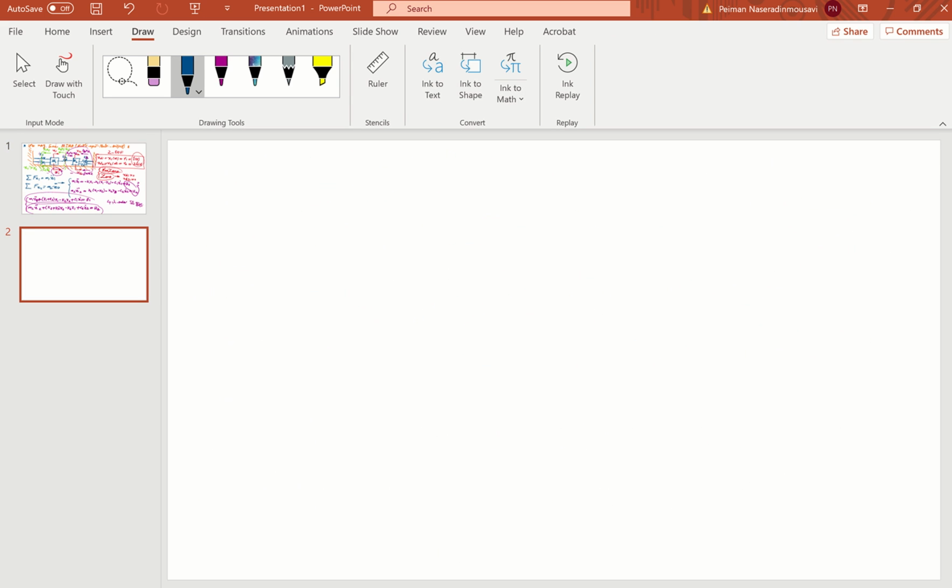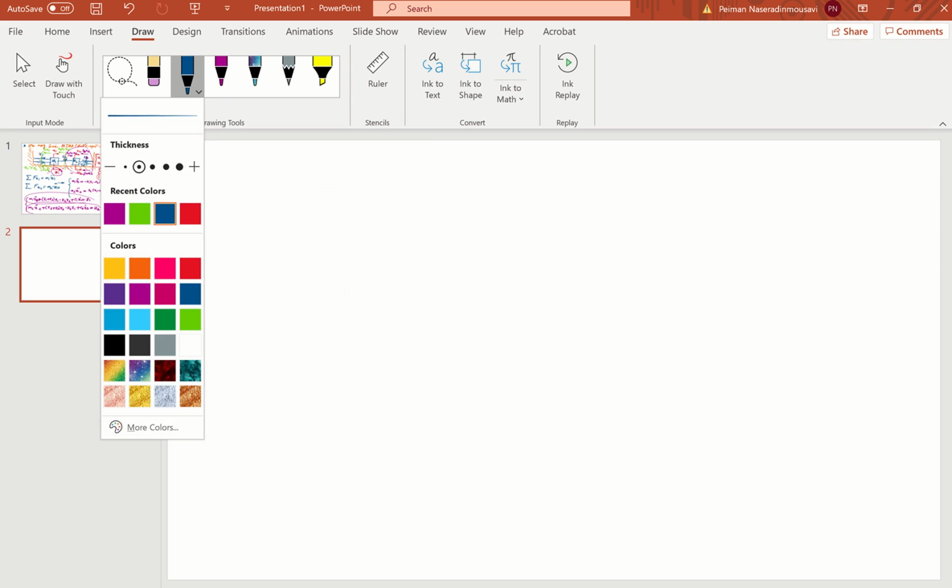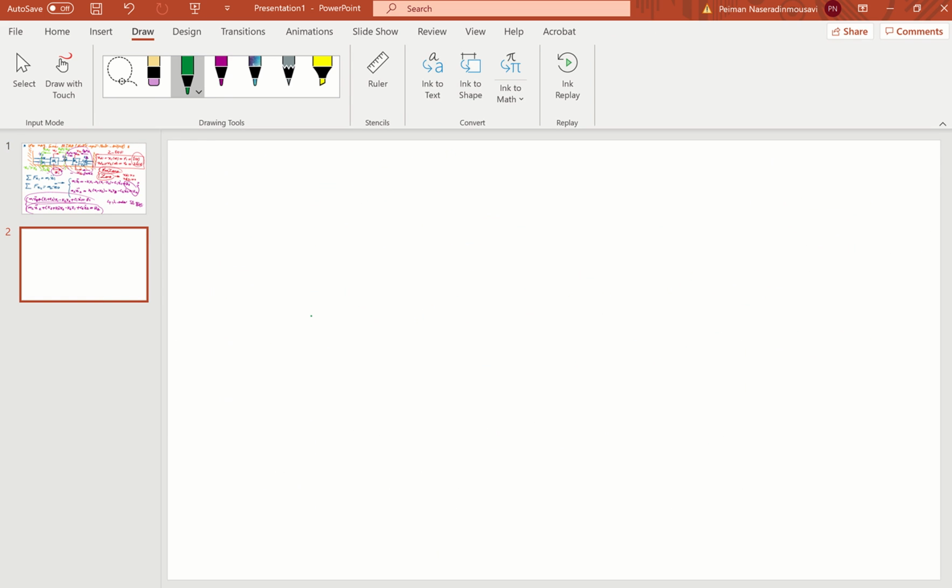Look at here, now you set up your state variables to be transferred to Matlab. You're gonna say, let me see this, M1 is x1, displacement of mass 1, and M2 is x dot 1, as we already defined. M3 gonna be x2, displacement of mass 2, M4 gonna be velocity of that mass.